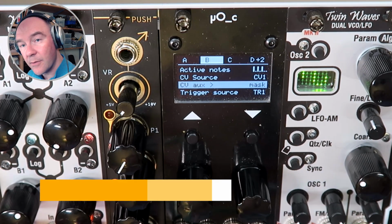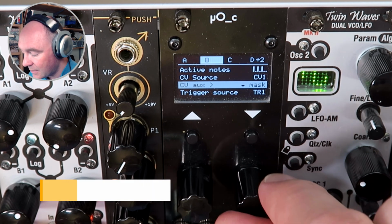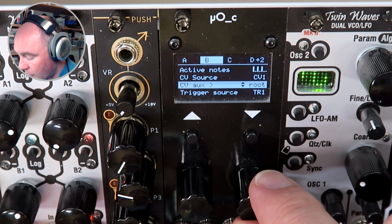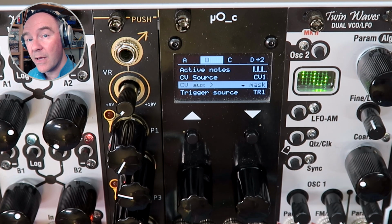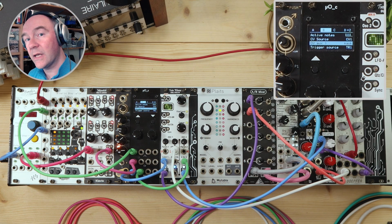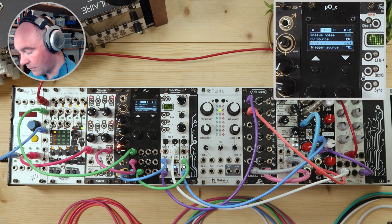We get a new little submenu appearing called CV aux. This lets us do things like CV mapping parameters in the quantizers. Now, there are not a lot of them you can map: root note, octave, transpose, and so on, but the one that's interesting is to map the scale mask rotation. Now, a control voltage on the CV2 input will rotate that scale mask for us. So like where I was turning the knob previously, we can now put it under CV control.